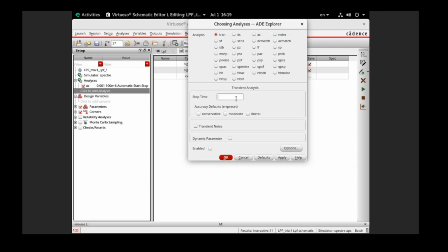One signal at the 1 kHz frequency, the -3 dB frequency, and one sinusoidal with frequency higher than 1 kHz, and we can start to observe. In that case, we will need a stop time that can accommodate all of the 3 analyses. Otherwise, we will have to add the same transient analysis and just change the stop time, which is very inconvenient, right? So you need to have the slowest stop time in order to accommodate the whole 3 cases.